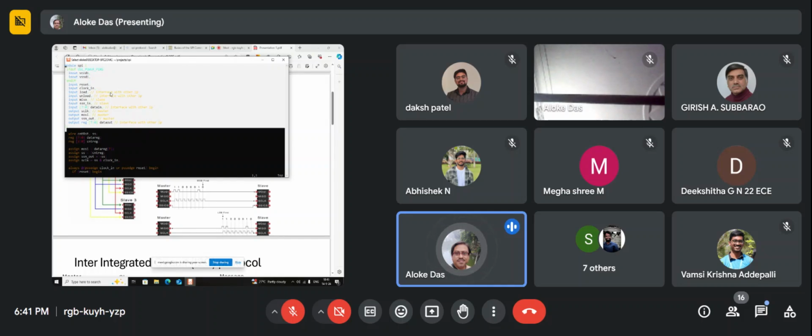And also think about your slave. Slave receives the data. Then what does it do? It will use it, right? Who will use it? SPI is just a protocol. Then on the slave's side also, there will be some other hardware which will use that data. So that hardware needs to unload the data.